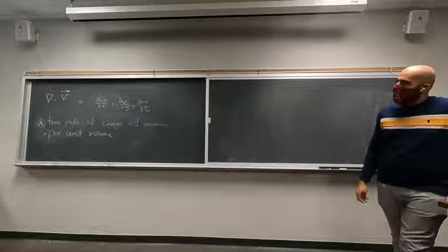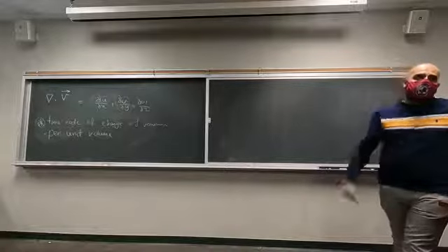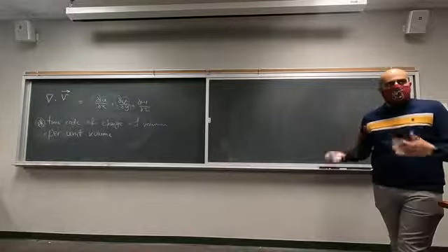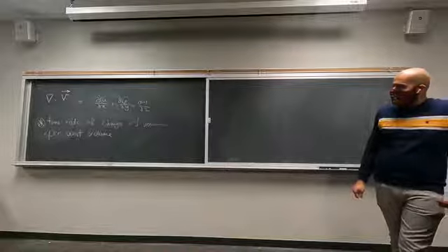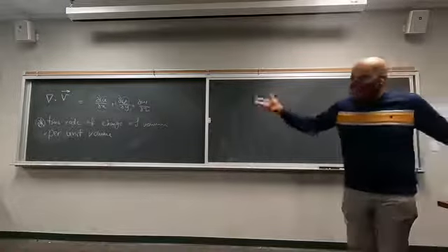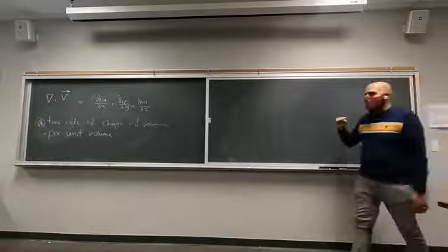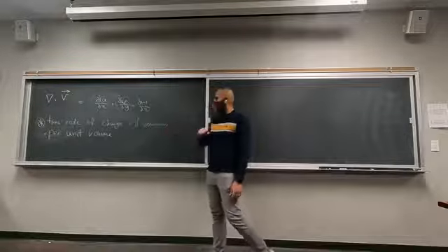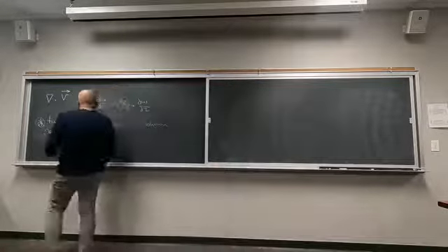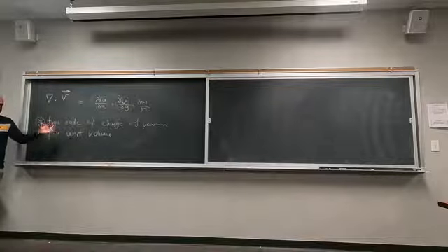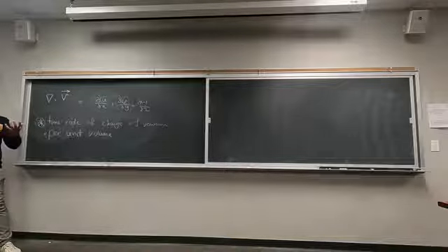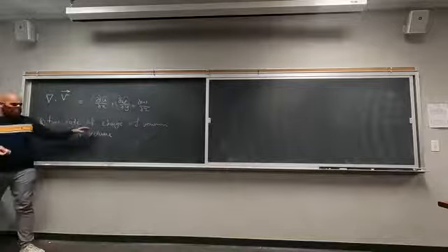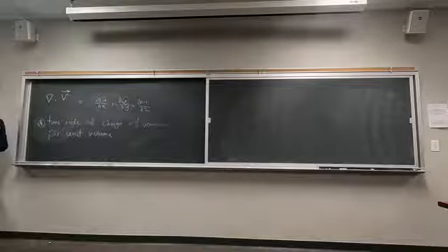Okay. So let's say we are dealing with an incompressible flow. We know what an incompressible flow is. We have talked about it, and you have seen it in your fluid mechanics course as well. What is the value of divergence of velocity for an incompressible flow if we take this definition as a representation of divergence of velocity? This is what divergence of velocity represents: time rate of change of volume per unit volume. This per unit volume part is just a normalization. We are normalizing the changes of volume. So this part is just nothing, right? It essentially represents the time rate of change of volume of a fluid element that has a volume of 1. Normalization.